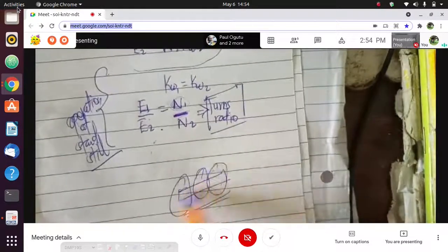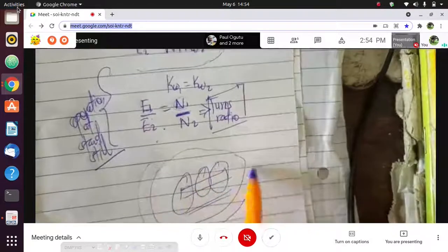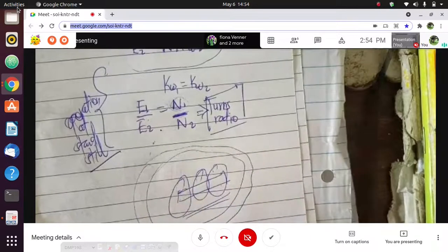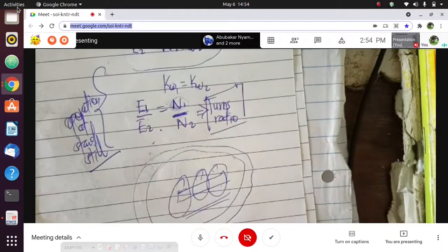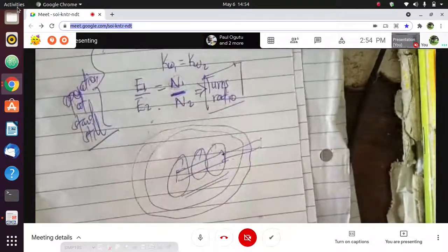And this magnetic field in the rotor circuit will interact with the rotating magnetic field in the air gap, which is produced by the stator winding. Because of these two magnetic fields linking, a deflecting torque is produced, enabling the rotor, which is connected to a shaft, to rotate.